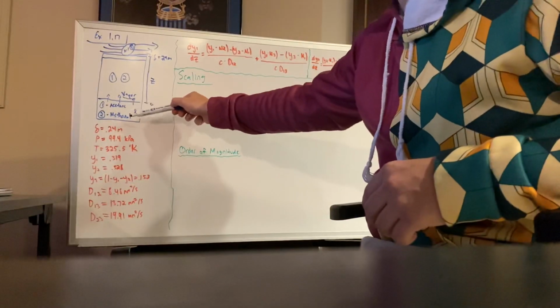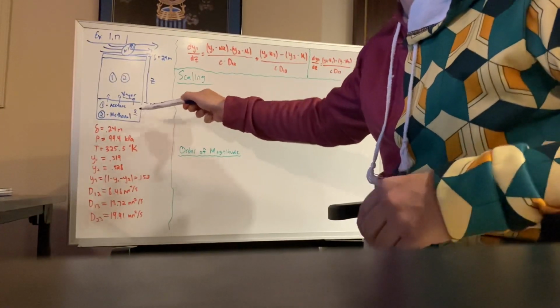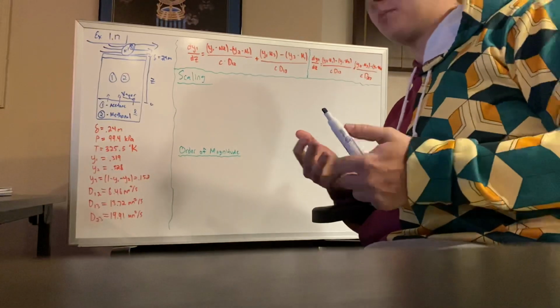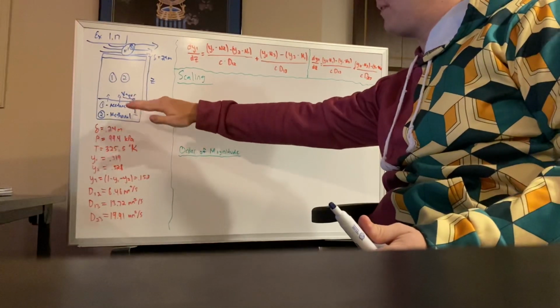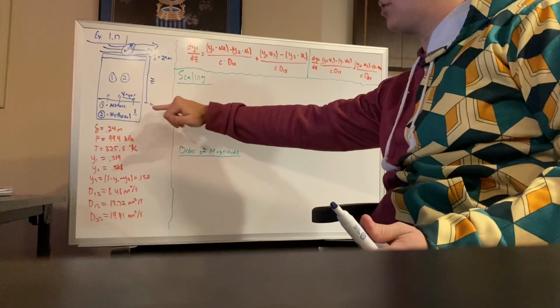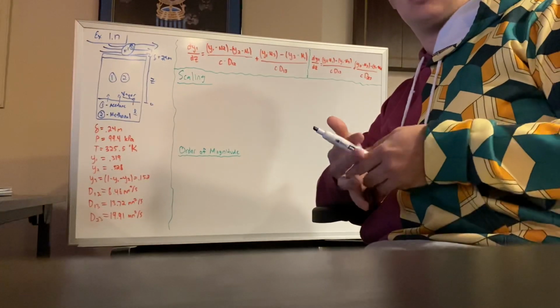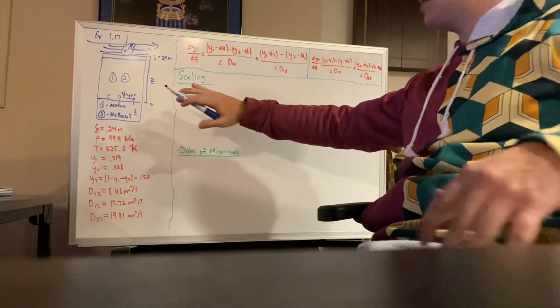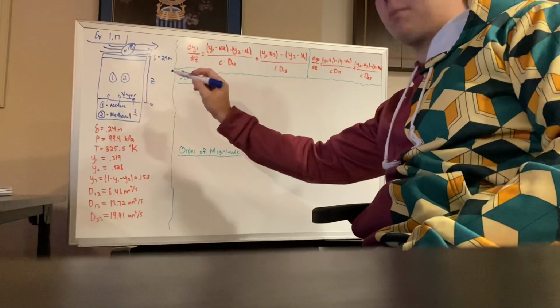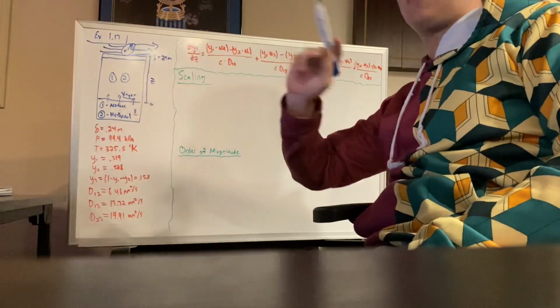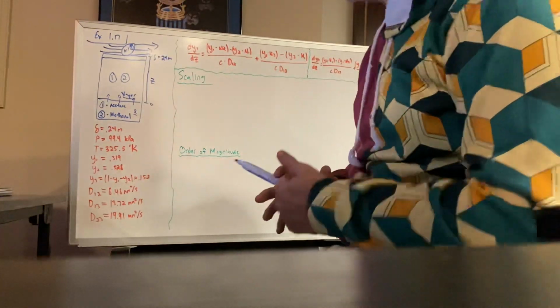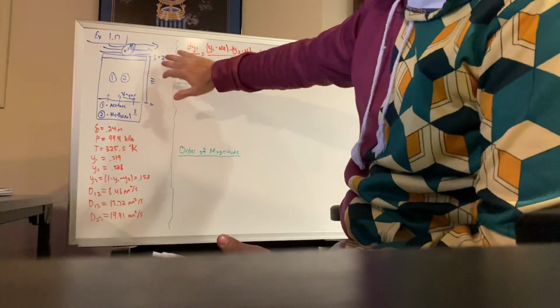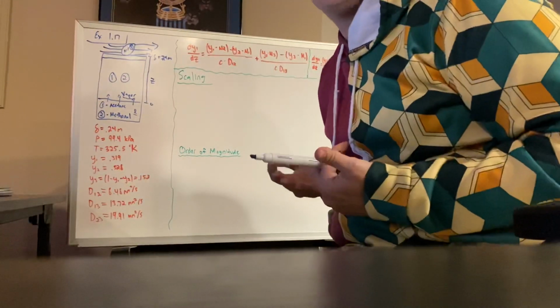So acetone and methanol are currently in the liquid phase at the bottom of the Stefan tube, where we are having that vapor-liquid interface represented as 0 along the Z-axis. And so Z is actually going to be the length of the tube where we only have vapor up until the screen and the air starts filtering over it. But the whole delta from that is actually 0.24 meters as a whole.